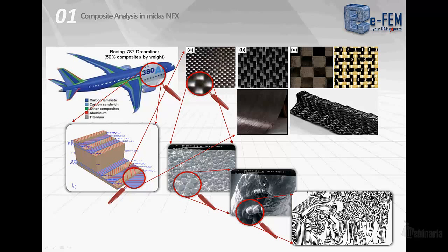If we go more in depth, we can see the fiber, and this length of investigation is useful to define maybe the mechanism of damage of the fiber itself. At this magnification, the fiber appears to be homogeneous. But if we go deeper, we see that the chemical structure of the fiber is made of plies, or better sheets of carbon molecules that are then wrapped together into the fiber itself.